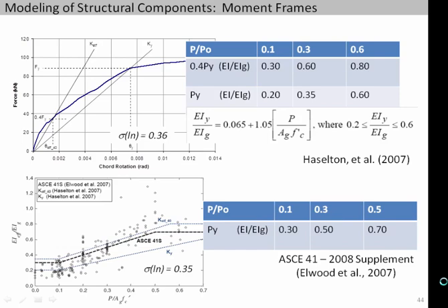So it changes whether you think you're doing a serviceability analysis, where you're not yielding components, versus whether you're doing a nonlinear analysis where you're going to be yielding, where your secant stiffness is up to yield. So much different values, so be aware if you're doing analyses with different expected drift or deformation levels.